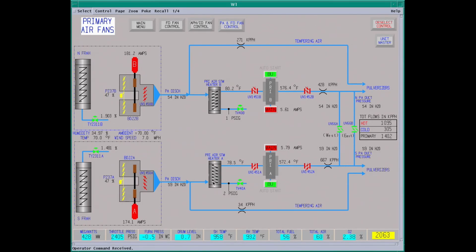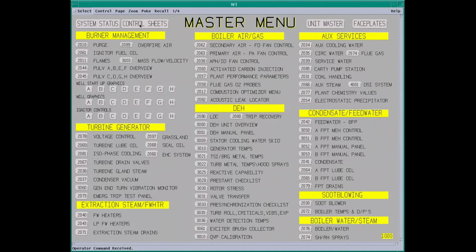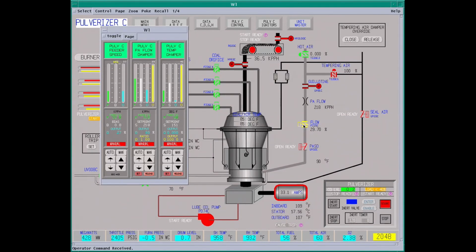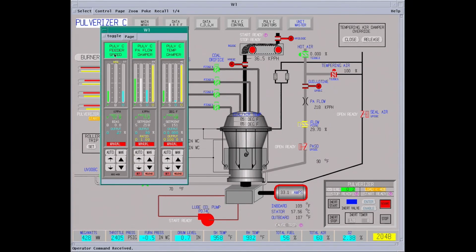We have an air heater system. We call it the FRA. It basically keeps the air warm so you don't drop sulfuric acid, nitric oxide acids and stuff on the plates and air preheater. Coming in the air preheater at 78 degrees. It's only heating at 572 degrees coming out. We need to get this light off, load less than 40% in order for this plant to start moving up towards the 500 megawatts.